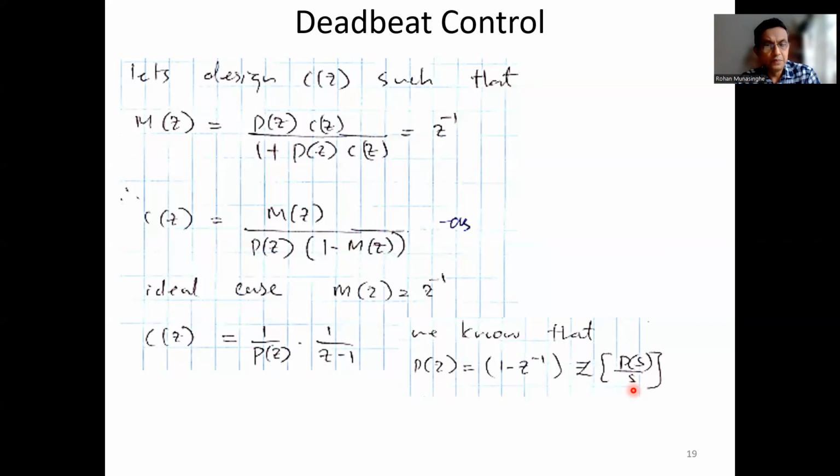You get PZ. And remember, when you continue this process, and if you get a result, it will be a Z transform or Z transfer function or Z expression, everything in Z world, right? And if you have anything in Z world, a polynomial, right, you can convert it back to time domain, which is a difference equation.